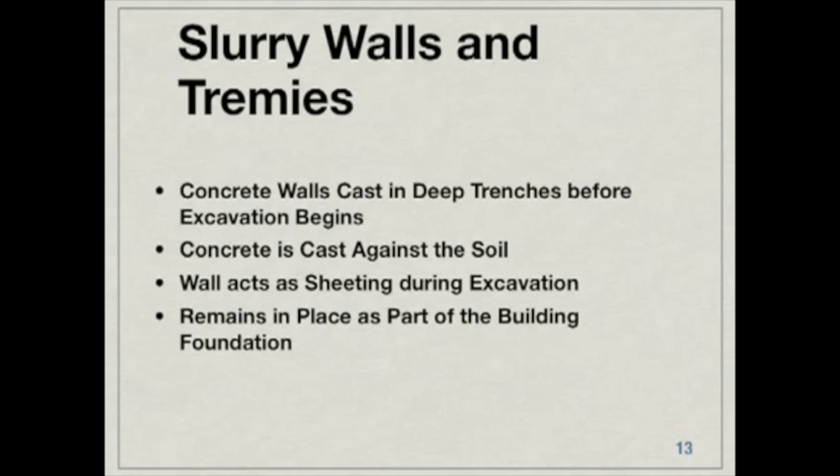Typically, the concrete, especially at the beginning, is a much richer mix. And also, you have to be placing this very, very slowly so that it doesn't get diluted by the slurry inside the wall. What I want to do now is go through this process step by step on the next couple of slides so that you get a bit of a feel for how it's done.